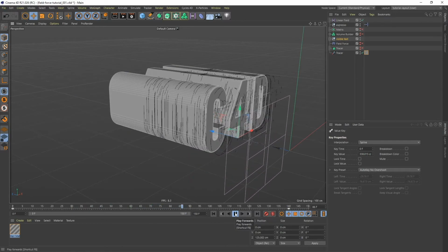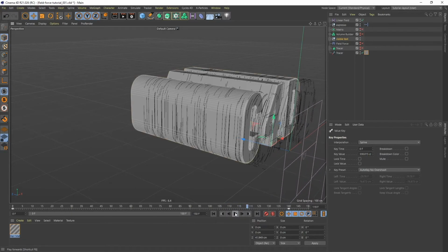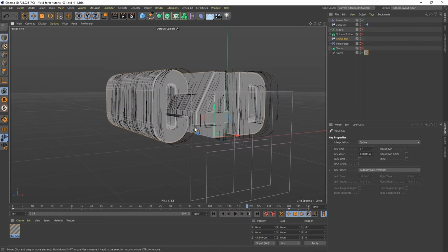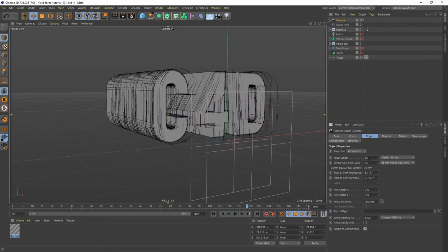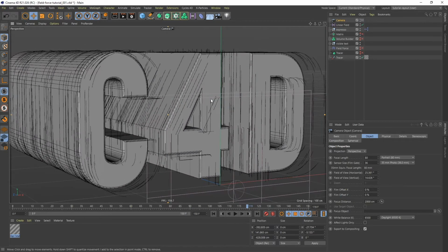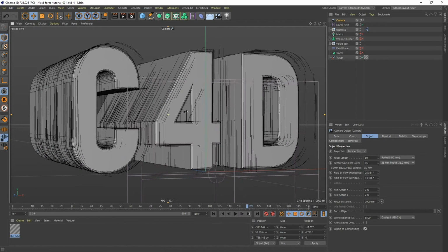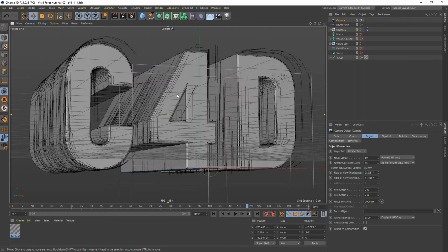And the keyframes by default are going to be easy ease, which is exactly what I want. So that's good. Let's choose a different type of camera. And let's look through the camera. And I want to have, instead of a 36, a longer lens, like an 80 millimeters. And then for the final framing, I think I want something like this, just so it becomes a little bit more majestic when you're looking up towards it like this.